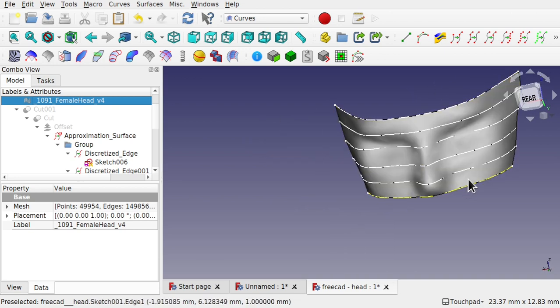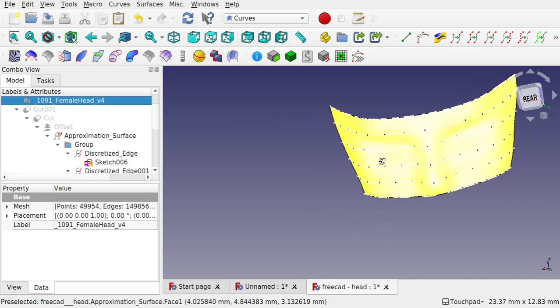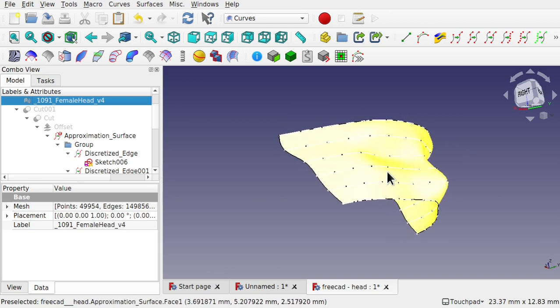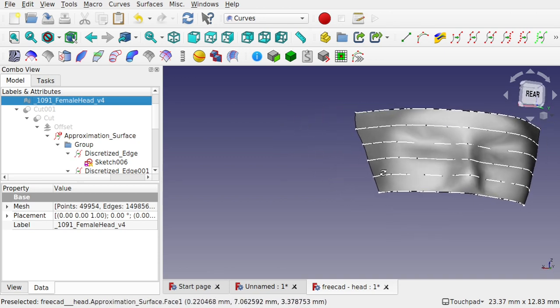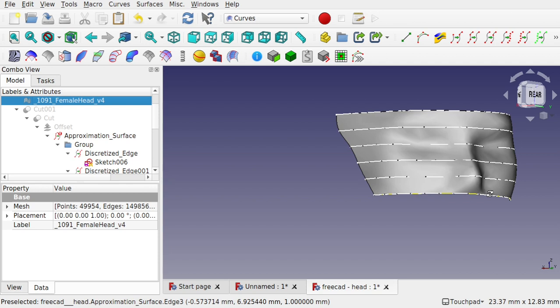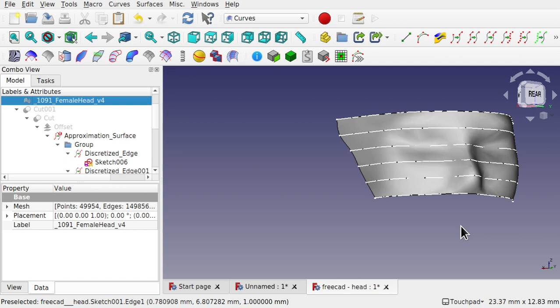And because we've taken each of these cross sections, then we've built up a profile of part of our model. So you can see how we use the Discretize tool to create those surfaces with single lines that we can divide up and create surfaces between those, and also through profiles like this in a group using the NURBS curves on a surface and using the approximate points to NURBS surface there.